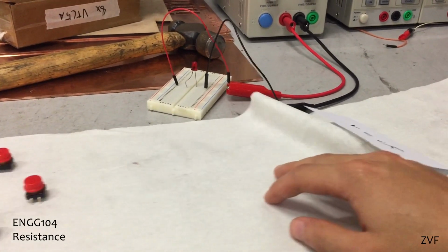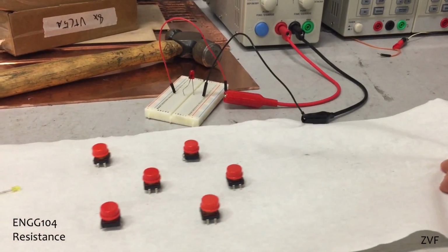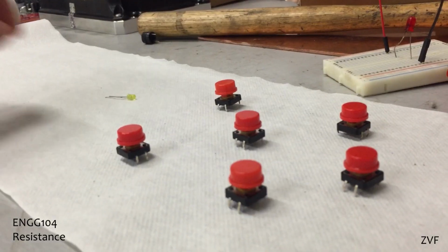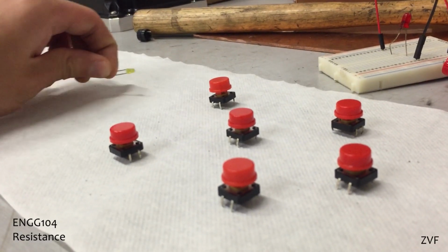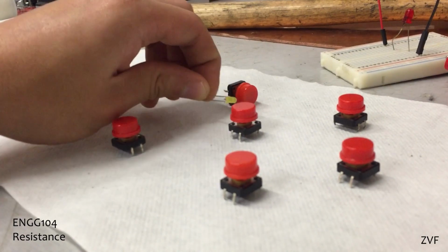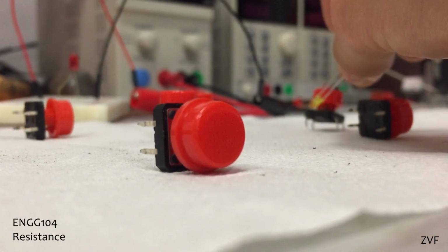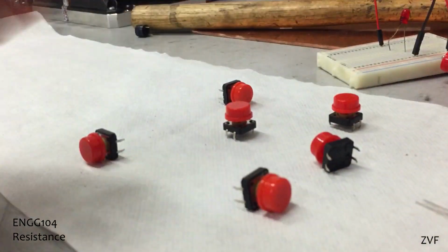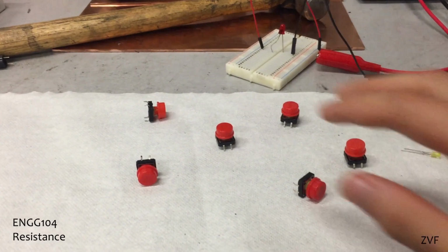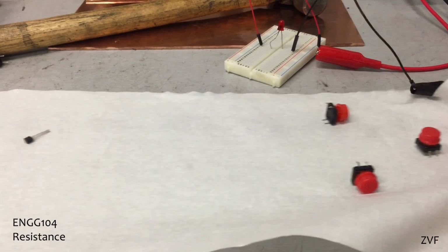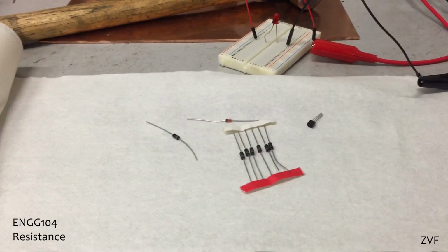In a conductor, resistance manifests due to the collisions between the conductor's electrons and the lattice structure of the conductor's atoms. The influence of these collisions is exacerbated by a more energized or excited lattice, and hence higher temperatures increase a conductor's resistance. This characteristic is denoted with a positive temperature coefficient.